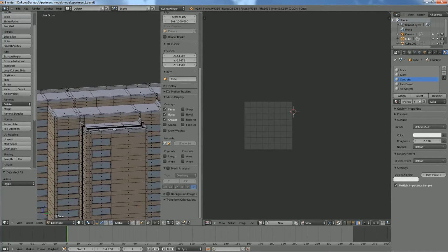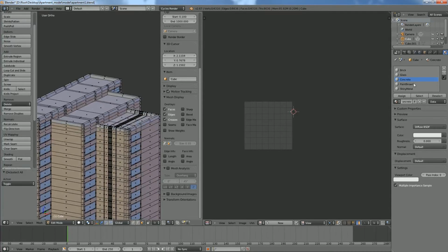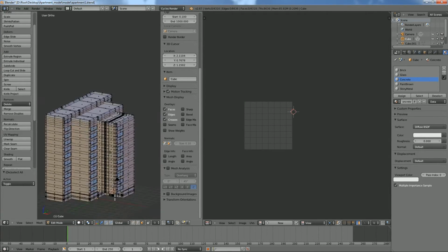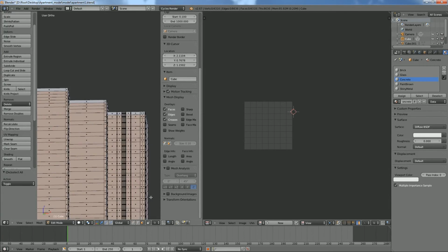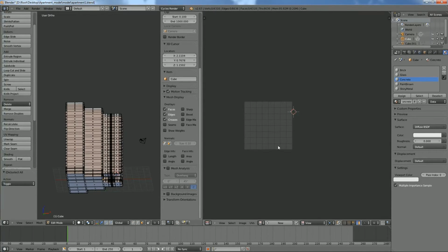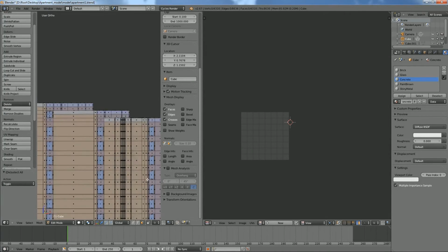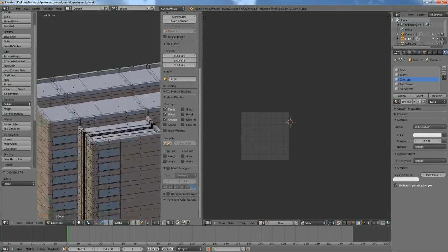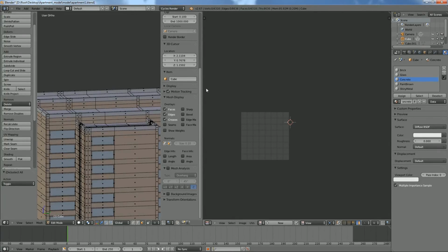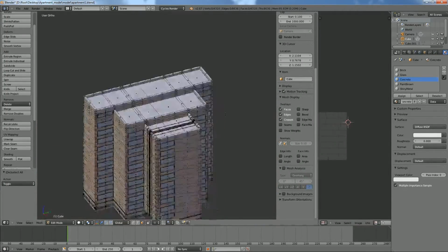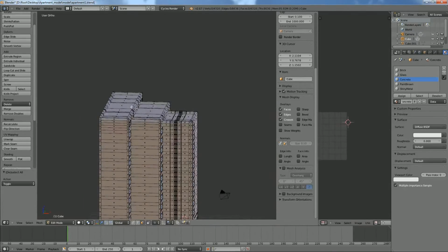So the door paint we'll be doing procedurally with nodes later, so we won't have to worry about unwrapping that, unless you want to, in which case by all means, they're just flat, project from view, worry about the rim if you want. And the shiny metal, if you wanted to have a specific grunge texture on those as well, you'd want to unwrap those. But we are not going to be worrying about that. You know, add whatever personal flair you want. So the building is unwrapped now.